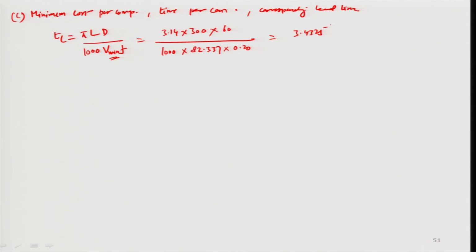So, if we want to determine the minimum cost in this particular case per component, this would be recorded as C0 T1, which is actually the non productive cost per piece, plus C0 Tc, which is the machining time cost per piece, plus C0 Td Tc by T, which is the tool changing cost per piece, plus finally the tooling cost, C1 Tc by